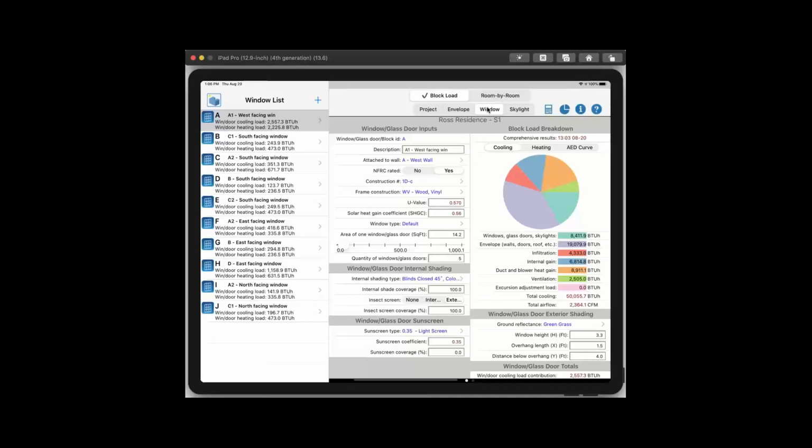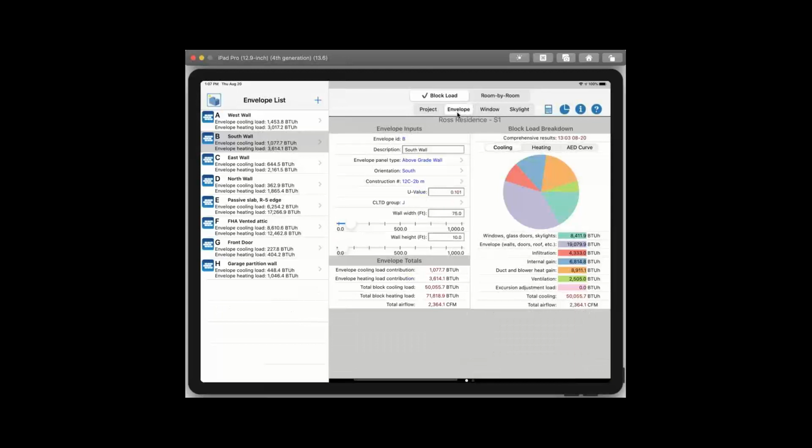So to me, it strikes me that having to specify a length and a width for the envelope features introduces a complexity that maybe you don't want. And again, maybe it's a Manual J protocol or something, but would it be possible to have a length and width entry or an area, and if you put in the area, then you're not required to do the other one? Because I do find myself coming up with these artificial lengths and widths just to get the area right.